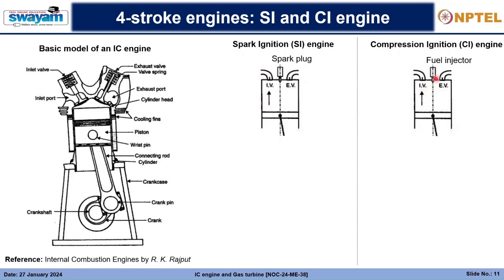The advantage here is that the two fuels used in these two cases are different. The fuel out here is injected at very high pressure and temperature conditions. So it is injected not in liquid drops that you can see, it is actually mist, very minute drops. That is also called the process of atomization. So atomization is quite important while you inject a fuel inside this chamber.